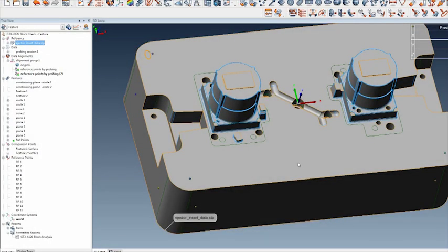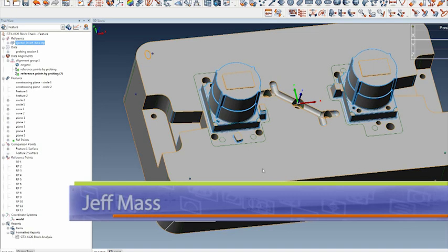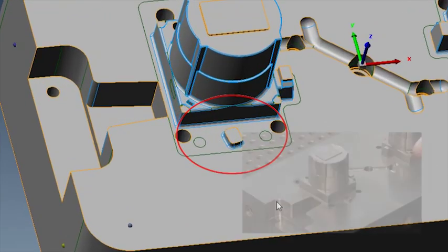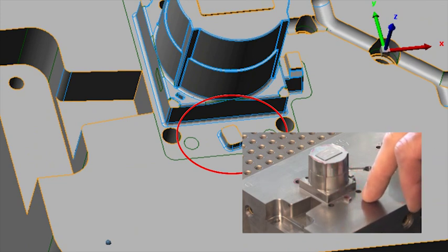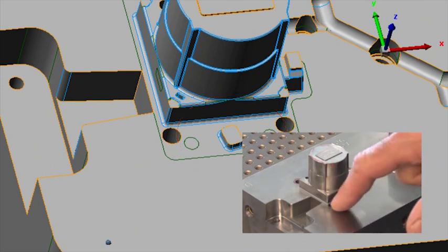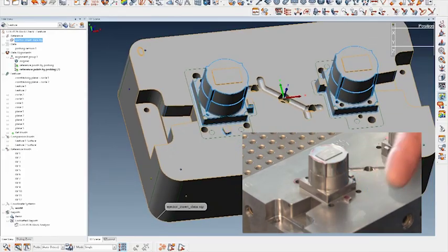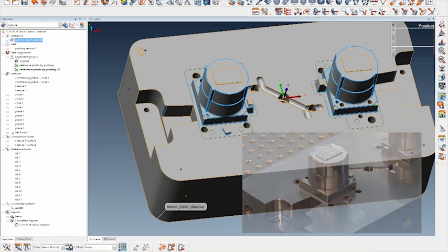This die block here that we're doing some analysis on, I've got PolyWorks V12 open right now, and what I've got is this little feature on that die block that is in question on its location. So what I want to do is measure up some of the edges of that with surface points or with some comparison points just to see how that compares back to the CAD.